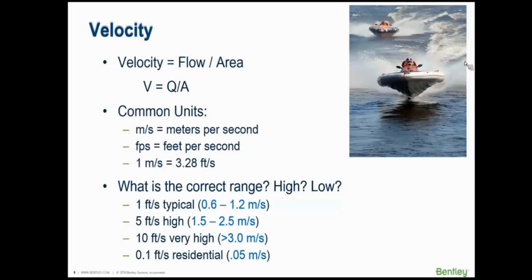As you get into the bigger transmission mains, usually they're flowing at a pretty good clip. They might get 3, 4, maybe even 5 feet per second on an average day. If you start getting above that, what happens? Well, you start getting a lot of head loss. You start using up a lot of energy. So the faster the water goes, as we'll see in some other equations, the more energy you're using, which is more pumping you've got to do.